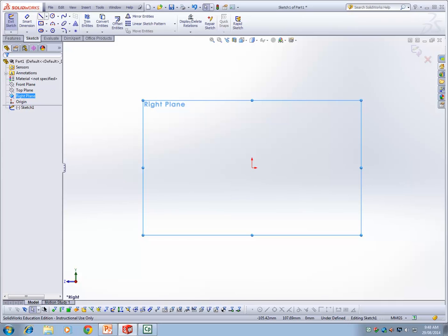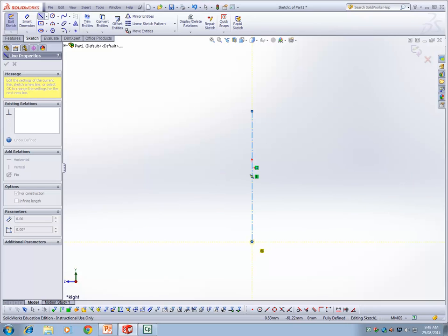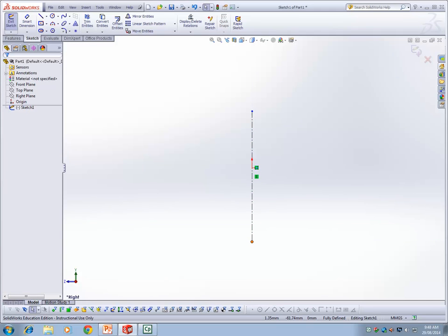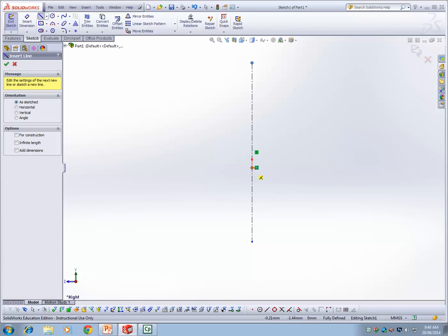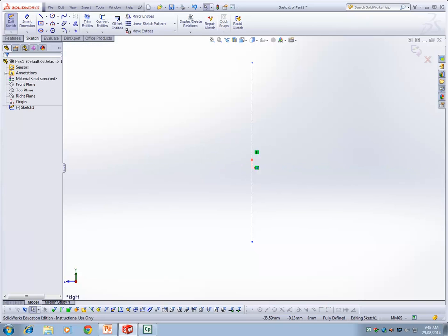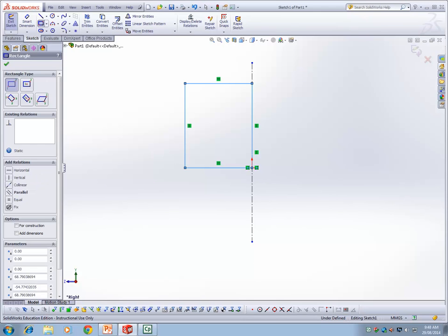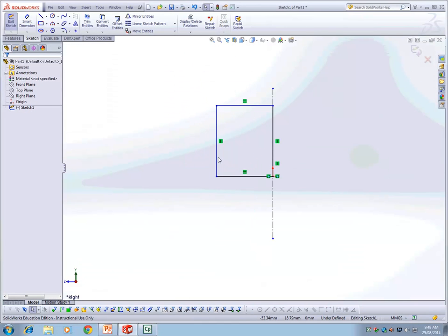You need first a center line. Snap your center line across your origin, then escape. Make it just bigger, then use a line entity, snap your origin point and draw a basic rectangle. Or you could select a corner to corner rectangle and snap the origin and place it here. So your rectangle is done across your center line, coinciding with the center line.